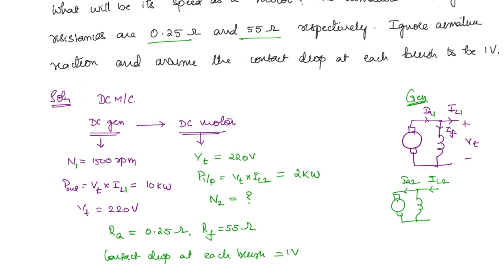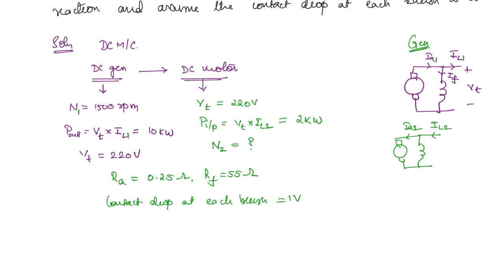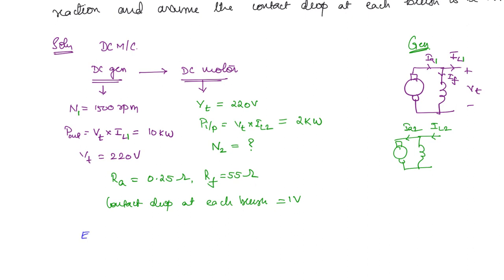So now this is essentially like two different cases. In one case speed is given, the other case you have to find speed. Okay. So we use the internal EMF expression. What is the expression for internal EMF? It is K phi n. Okay. If you use omega, then this value of constant will change. Okay. But it will be a constant nevertheless.